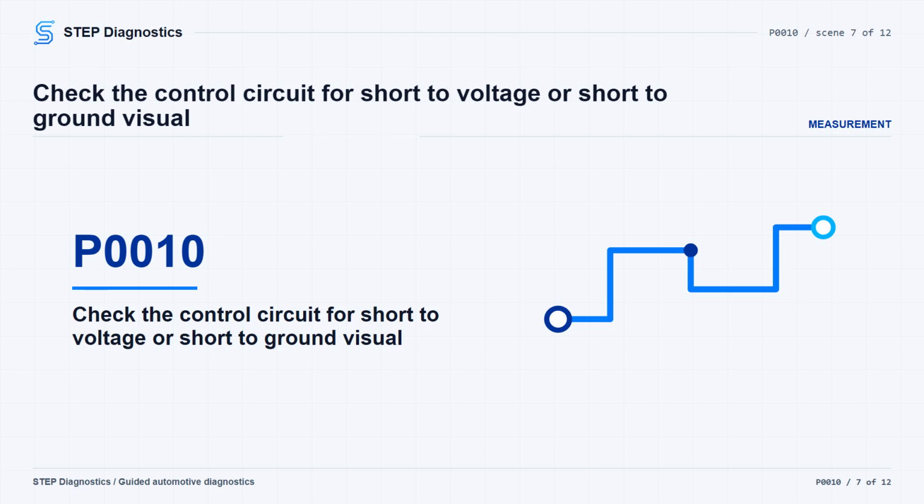If the lamp does not turn on with the solenoid commanded off, remove the lamp and command the solenoid valve on. The low voltage test status should be OK or not run. If it is not, power down. Disconnect the engine control module connector and test for infinite resistance between control circuit terminal 2B at the component harness and ground. Less than infinite resistance means repair the short to ground. Infinite resistance points to replacing the engine control module.